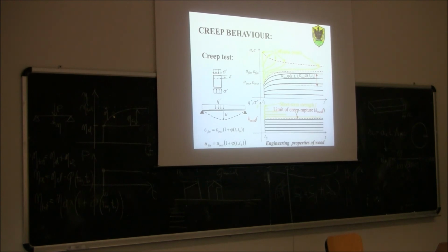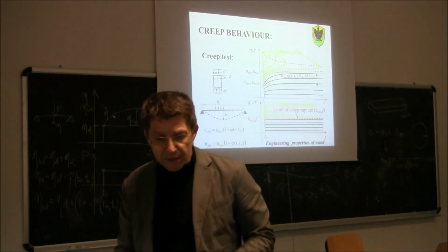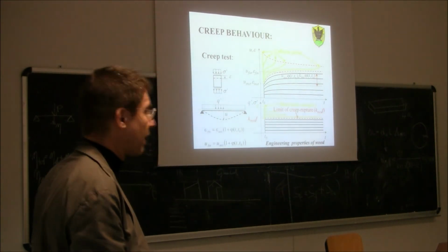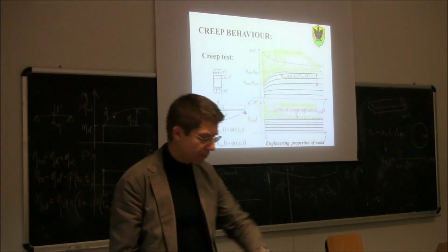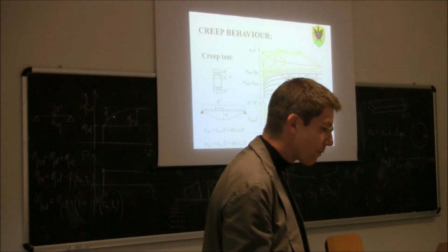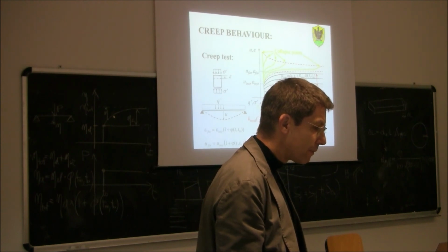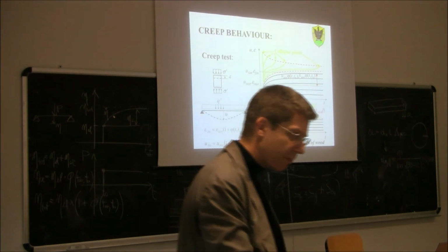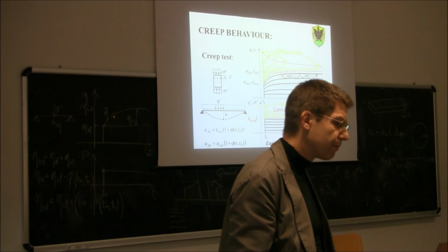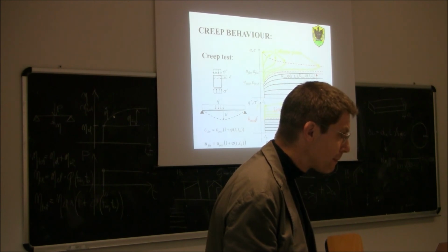Here you can see the connection between the creep phenomenon that we use to calculate the deflection of the beam and the dependency of the strength on the load duration. So the K mod factor that we saw before, until the K mod line, corresponds to 50% of the strength. I have a viscoelastic period. This is an approximation. Strictly speaking, it's not linear creep, but for simplicity, let's say it's a viscoelastic behavior. Then, separated by this line, I will have only creep.